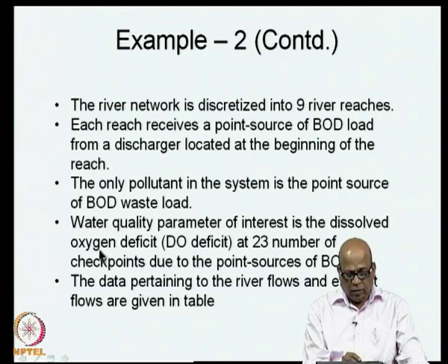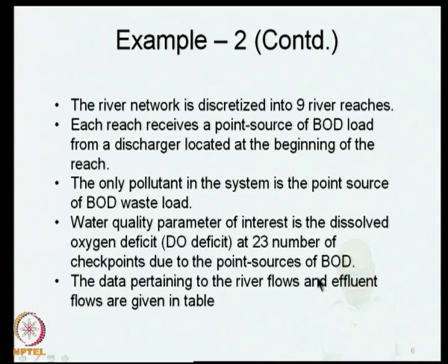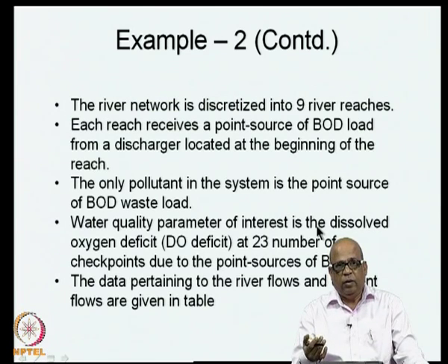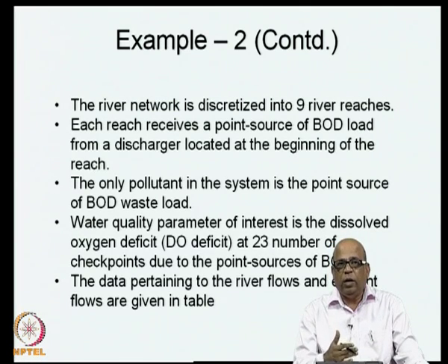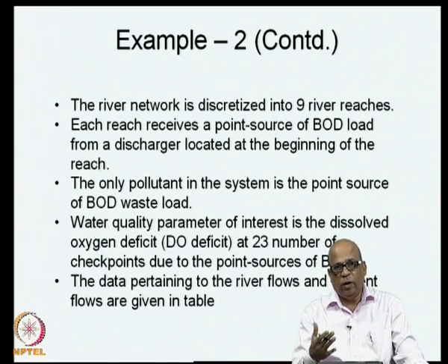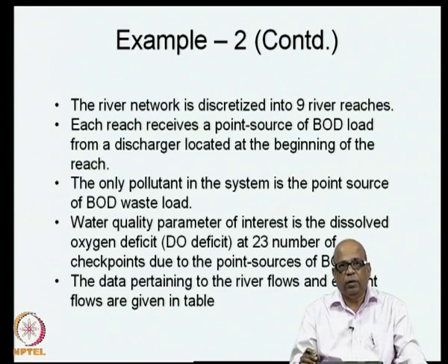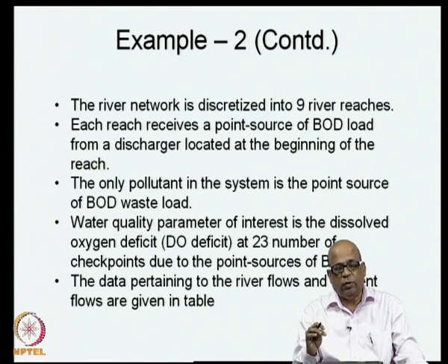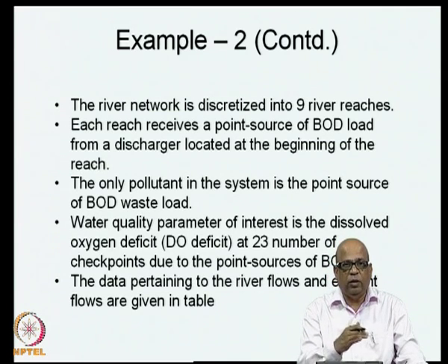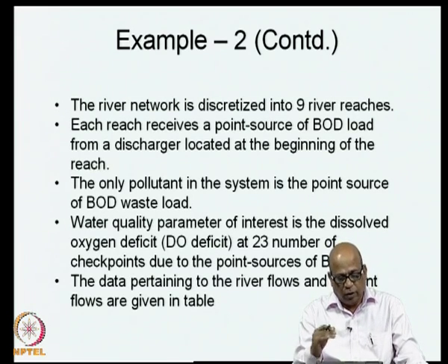We will also have the data pertaining to the river flows, effluent flows, etc., available. Then, you are relating BOD and DO. You may use the classical Streeter-Phelps equations to relate the BOD and DO at a particular location, that is, DO at a particular location with respect to the BOD loads at upstream locations. You will relate using the Streeter-Phelps equations, and the parameters for the Streeter-Phelps equations, which typically change from one reach to another reach in this problem, are also given. So, these are all part of the data.